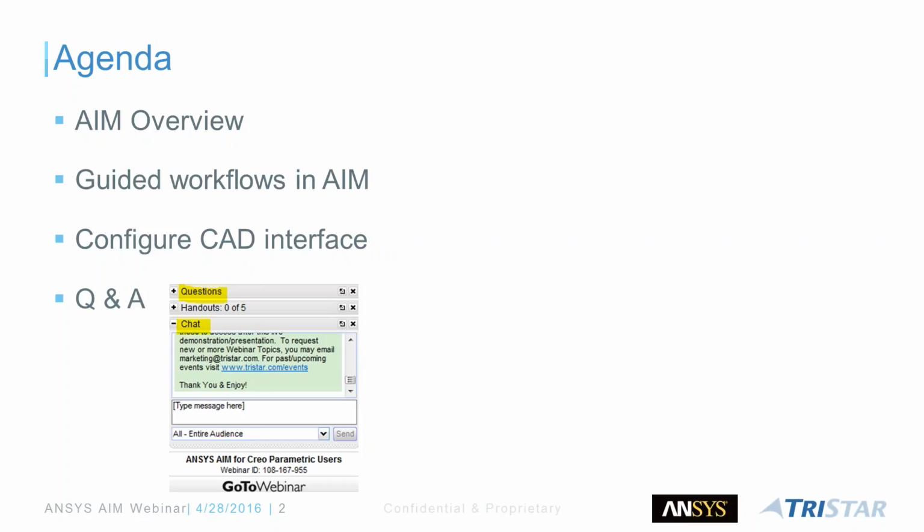You don't have to be an analyst to do the analysis. It's meant for the designer and the engineer, right? You can also configure your CAD. It's mainly Creo Parametric, so you can access or launch AIM from within the CAD. And you can also expose the parameters, dimensions, what have you, for doing design exploration within AIM.